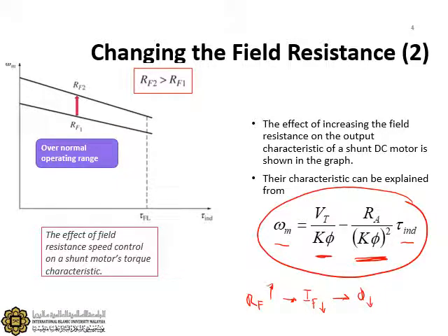And you can see from these equations, when the flux is lowered, first the bias will be larger. This bias here will be larger, and that's why you can see the line actually shifted. On the graph, the line is shifted up, right? Okay, and secondly, when the flux is reduced, the gradient is also affected.